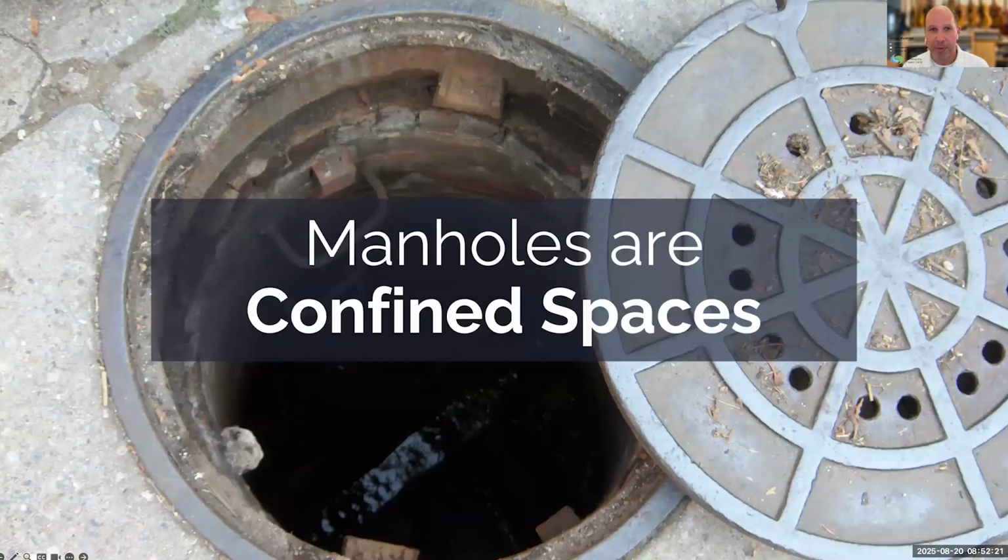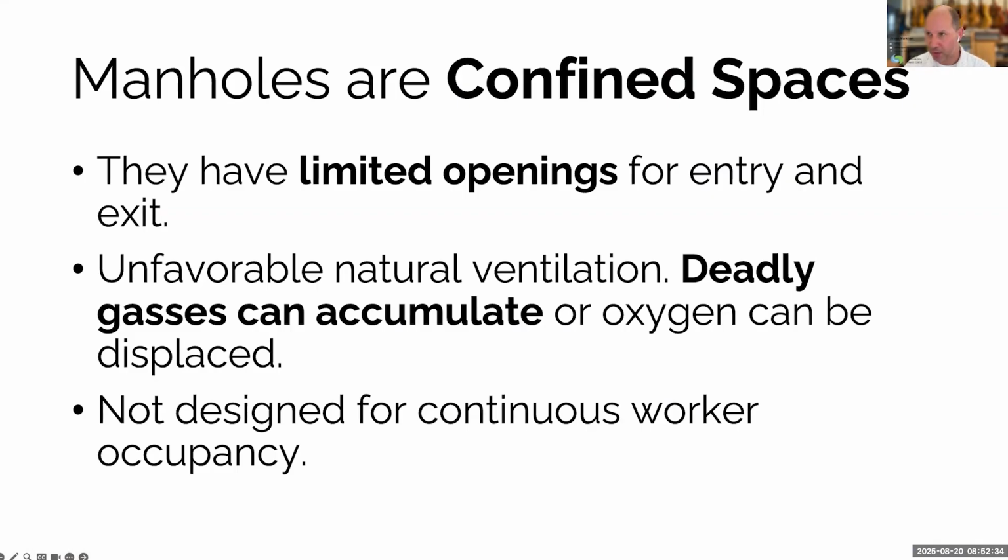Other important things to remember about manholes, they are confined spaces. Like I said, we'll do a safety specific training, but manholes are very, very dangerous. This is another place where operators die every year because they don't follow the rules. They're defined as confined spaces because they've got limited openings for entry and exit. They're not designed to be continuously occupied. And unfortunately, because there's sewage down there, deadly gases can accumulate depending on what's going on, particularly if you're going in for a blockage.